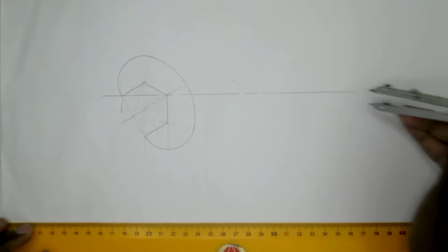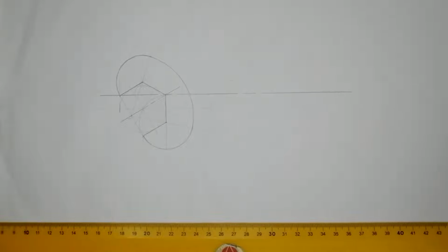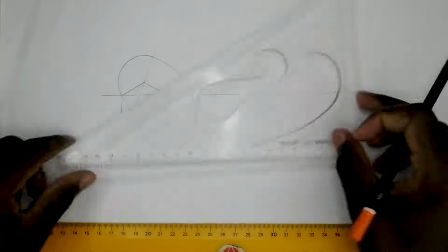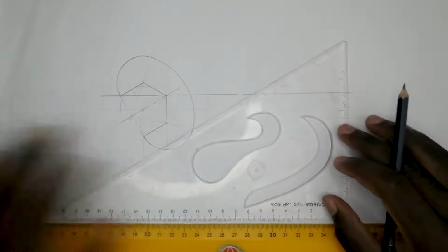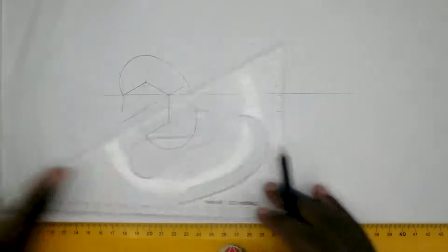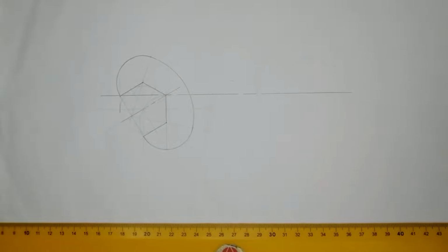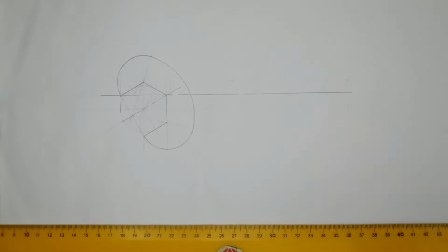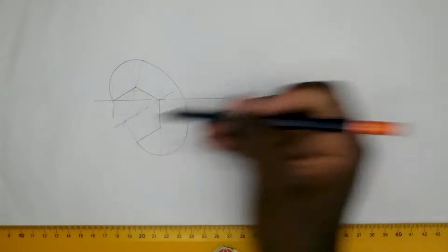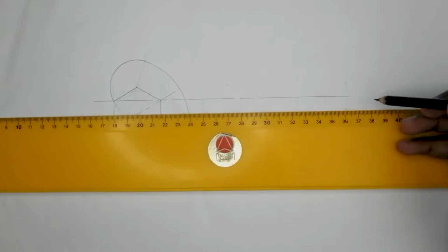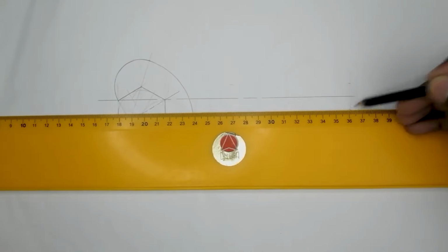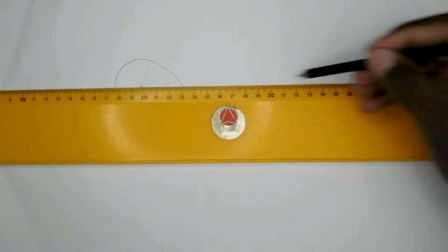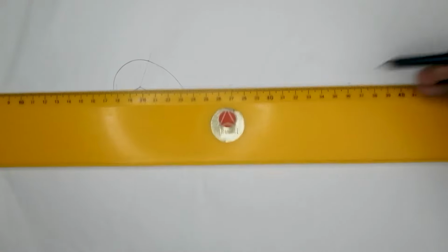you can mark a parallel line, or if you like, some people won't like drawing those two parallel lines, you can, on this line that we have, just draw a small vertical line, and then on this line you mark your distances. Then using a t-square, you can just draw a line from this point going to your left and from that point going to your left. So these lines I draw are in construction. I only outline them after I have drawn my arc tangents. So you can see that's my part with the handle.